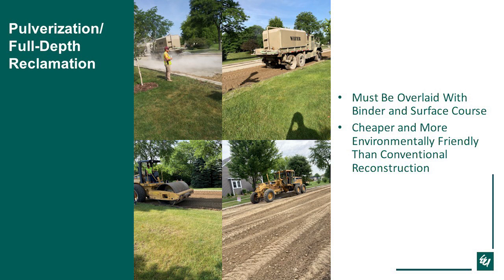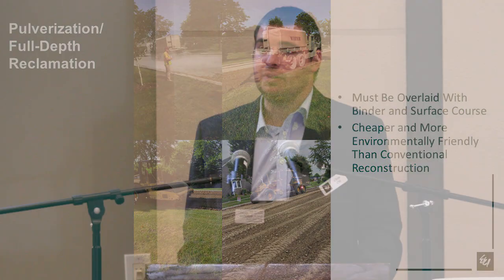And then there's a water truck that will hook up to the reclaimer, introduce the water, and mix the material back up. And then what's in that bottom right would just be your traditional road grader grading out the new base. They'll roll and compact it, and then let it cure. One thing that you want to do with the full depth reclamation with cement is to check for whether or not you need to do micro cracking.